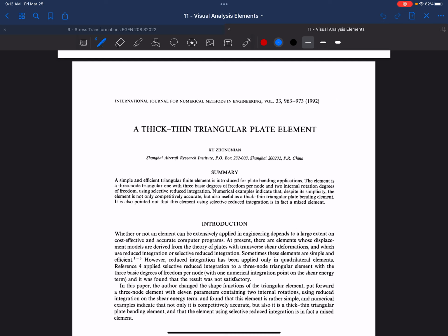Because as you guys know from concrete, it's not that hard to design a concrete footing. It's essentially one way or two way action in a concrete slab, right? You have punching shear, one way shear, and one way bending in two directions. So you do some minimum steel calculations, and it's pretty quick to do it by hand.